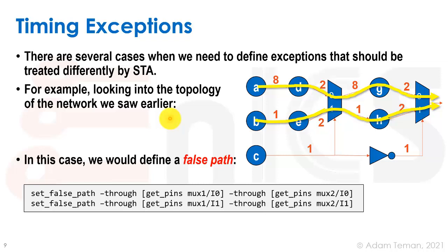And maybe our timing analysis will say that everything's okay, or in a worst case, it's going to screw us over, it's going to tell us that everything's not okay, and it's just because we didn't set a false path. This is a big part of a timing analysis engineer, going over the false paths and making sure that false paths are correct or not correct and putting them in the right place. It's something that the timing analysis or back-end engineer is going to be sitting with the designer a lot and trying to figure out.